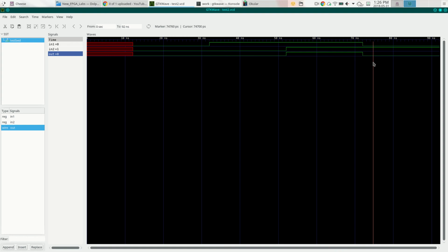And when we're using the full-blown FPGA software, we're still putting in Verilog, but the FPGA software is a lot more complex. This is basically 3 steps: compile, execute, look at the results. The FPGA stuff will run through dozens of steps, and it'll do things like timing analysis and glitch analysis and power analysis and all sorts of things like that.